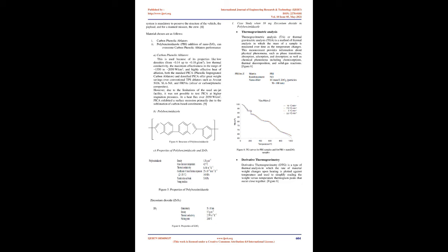Along with it, the ablative material should also have high enthalpy of phase changes, specific heat, and thermal shock resistance. A low thermal conductivity is necessary to prevent heat flux from entering the system. The dimensional erosion of the surface should be relatively low, uniform, and predictable. Gaseous species formed by material degradation should be of low molecular weight, and the material should be of lower density.